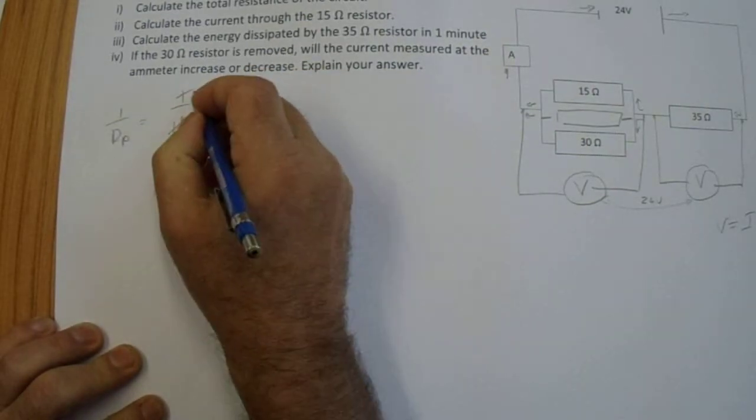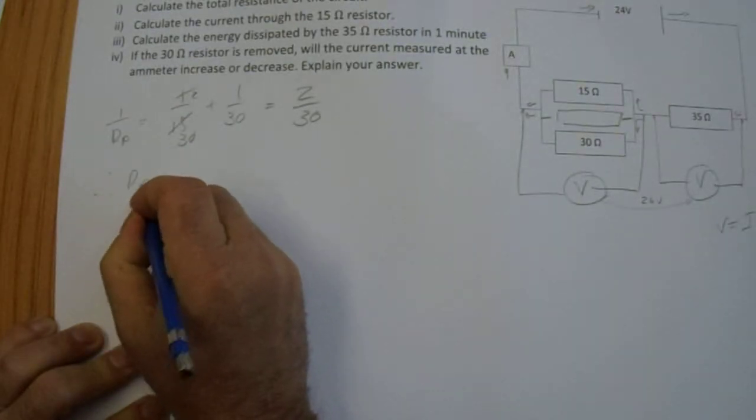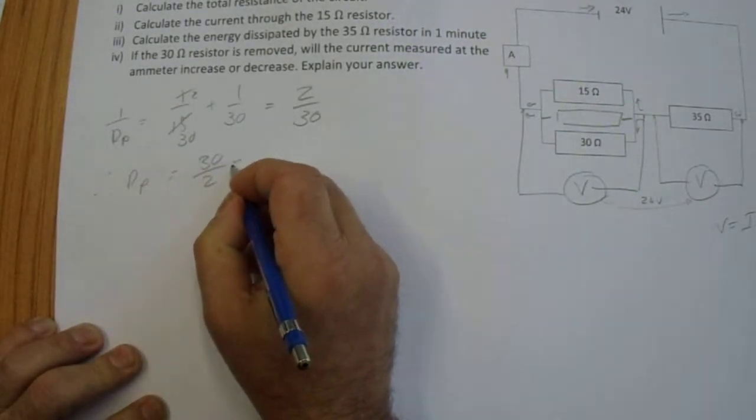The total resistance. Well, the total resistance is based on these three resistors. We have a 35 ohm resistor, and that's in series with these two resistors, but these two are in parallel. So we first have to calculate the parallel resistance of these two and represent them as an imaginary resistor in series. So 1 over R parallel equals 1 over 15 plus 1 over 30. If we change that to 30, that will become 2, so it equals 2 over 30. Therefore, R parallel equals 30 over 2, which equals,